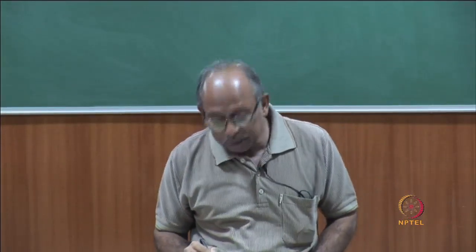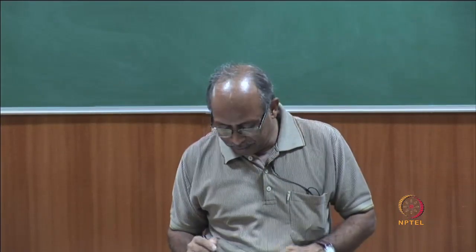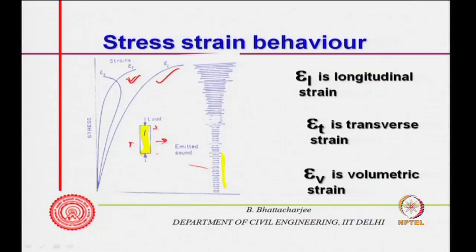So, what has been observed here? That is actually acoustic emission. In a systematic manner, one can trace this. As I increase the load, initially the emitted sound is very, very little, and then it goes on increasing; a lot more sound is emitted as the loading progresses. In other words, permanent deformations and non-linearity are related to a lot of cracking, and this is confirmed by ultrasonic pulse velocity also,